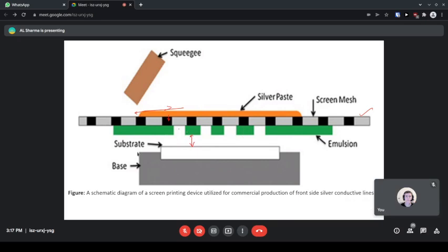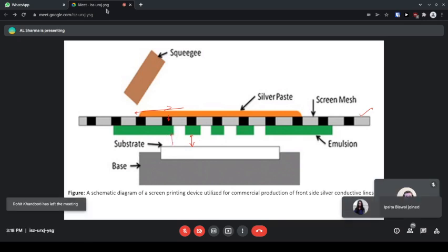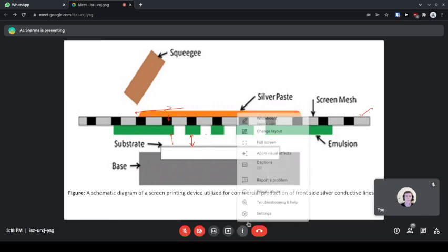So that thickness, and the mesh that is given, the paste is going to perfectly cover this area, and that is going to control how close you are putting this mesh and this substrate. So the distance between this substrate and this mesh is going to control the thickness of your material sample, meaning your thin films. So thin films are going to be prepared using this screen printing technique.